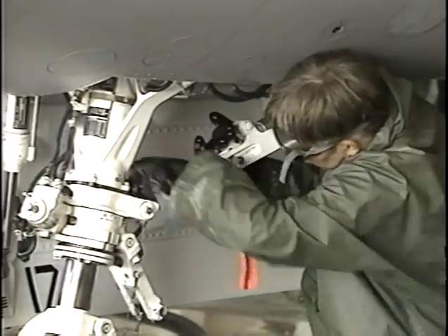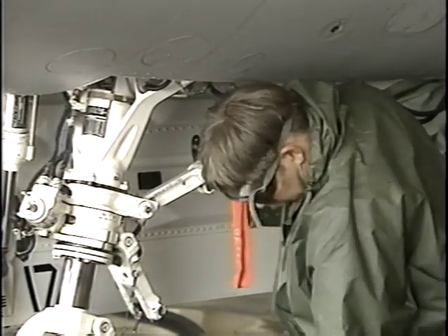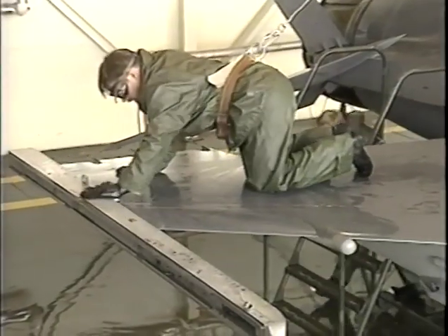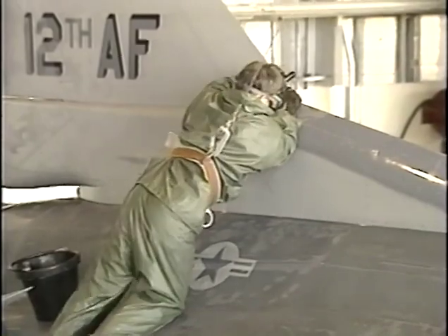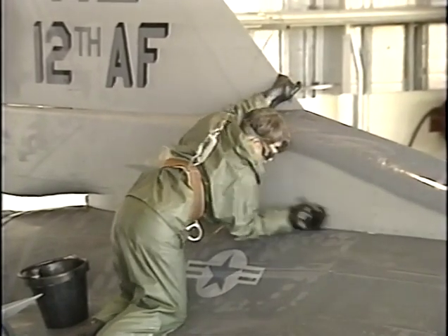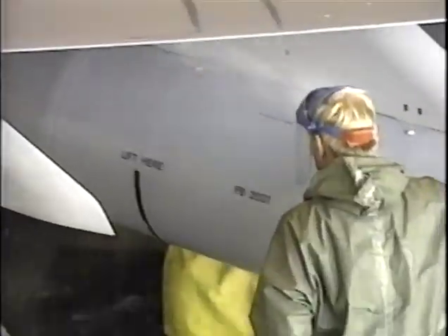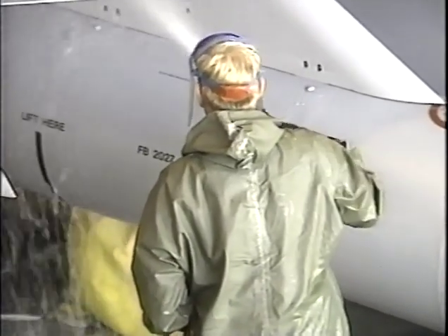When you're scrubbing the aircraft, clean the heavily soiled areas thoroughly. Remember, grease and heavy dirt deposits can promote corrosion faster than other areas. Rinsing the aircraft is just as important as scrubbing it. Aircraft cleaners, if not thoroughly removed, will cause a chemical reaction with the metal surfaces.